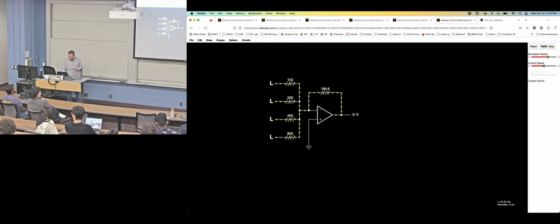So here we have different resistor values. They're going to produce different currents. Now, the analog value that's coming in here is just going to be 5 volts or 0 volts, so it's some binary value. So now I get to choose a binary value in here, and it's going to have different proportional currents according to the resistor that it's dropped over. If you remember your painful op amps, for some odd reason, it's trying to drive the negative pin to 0. Now, don't know why, it's fine. Let's just accept that that happens.